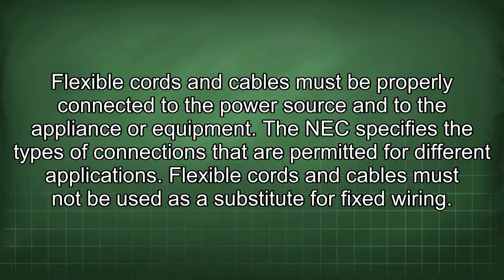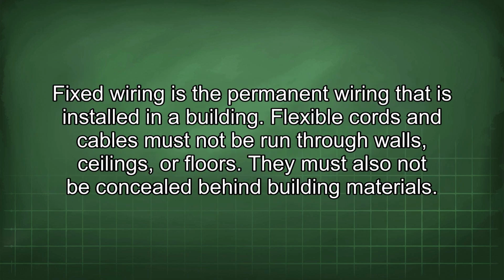Flexible cords and cables must be properly connected to the power source and to the appliance or equipment. The NEC specifies the types of connections that are permitted for different applications. Flexible cords and cables must not be used as a substitute for fixed wiring. Fixed wiring is the permanent wiring that is installed in a building.